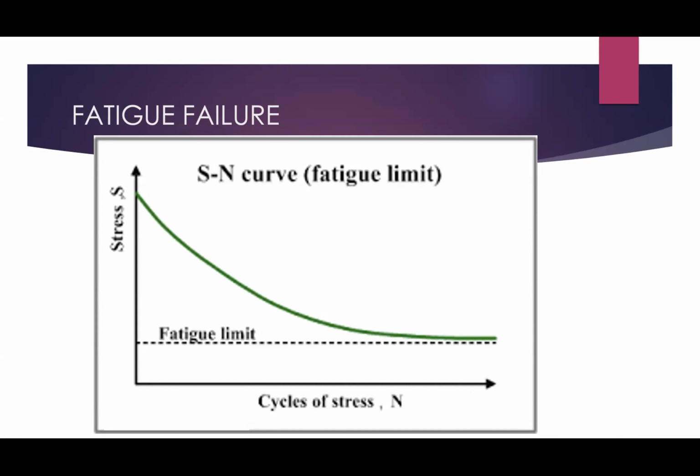And the way that came about is because we assume that we do 1 million cycles of loading per year. So if a material can withstand 10 million cycles, in effect, it will last 10 years. So your goal as a manufacturer is to keep a material operating at a level below the endurance limit, because in theory, in vitro, it will last forever. So with a hip, it's always operating below the endurance limit because a hip is a very congruent surface, high contact surface area, round on round, low contact stress, therefore it sits below the endurance limit.